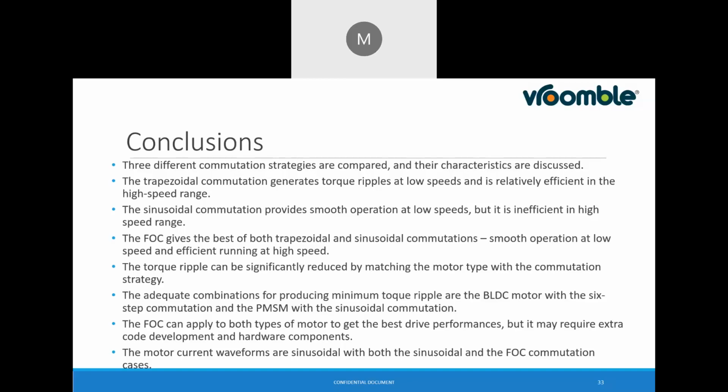That is the first thing. In that condition, the pole pairs will be limited. Now, I am removing the brush. I am making it a brushless DC motor. But now I want to vary the speed. Once I give a DC supply, it will attain a constant speed. But I want a three phase. The magnet will remain the same as in a DC motor, but at the winding side, I will wind in three phase.